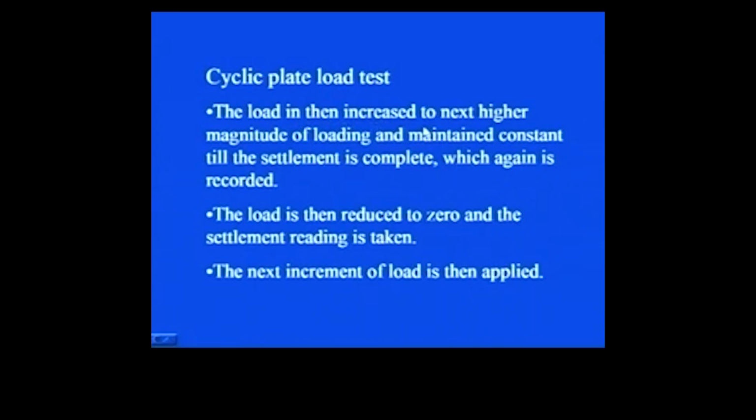The load is then increased to the next higher magnitude of loading and maintained constant till the settlement is complete, which again is recorded. So once you have loaded and then unloaded to 0, further loading takes place, and in exactly the same manner as the first loading cycle, you do the second loading cycle.